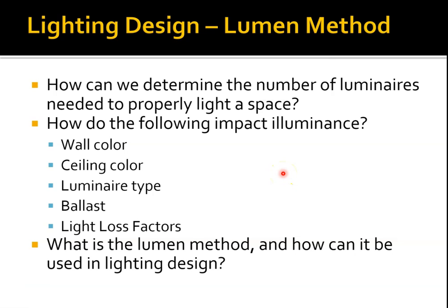So in this discussion, I'm going to go over the Lumen method. The Lumen method is used as a way to approximate the number of luminaires you need, or if you know the number of luminaires and all the other details, you can figure out how bright a surface is going to be, or the illuminance in the room.